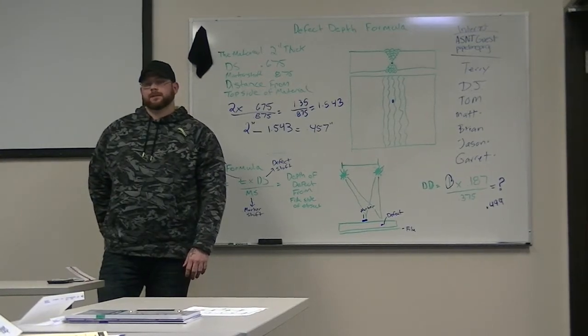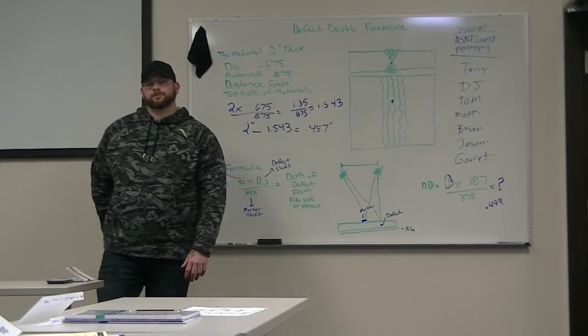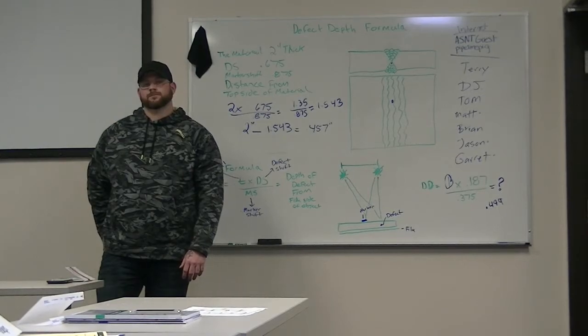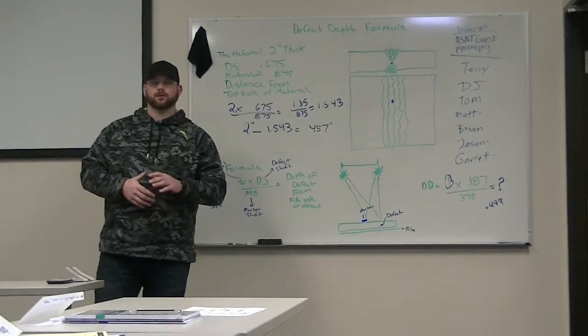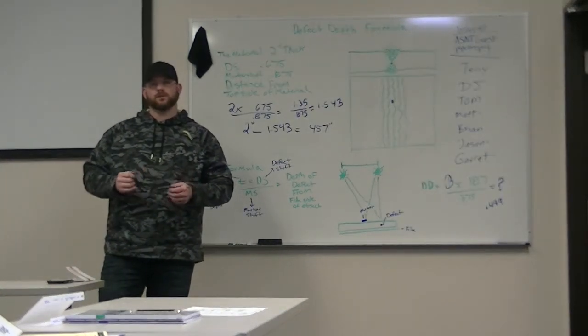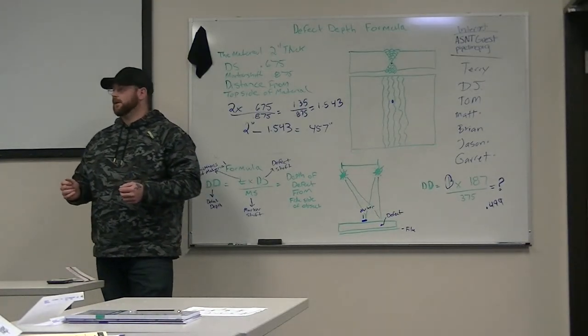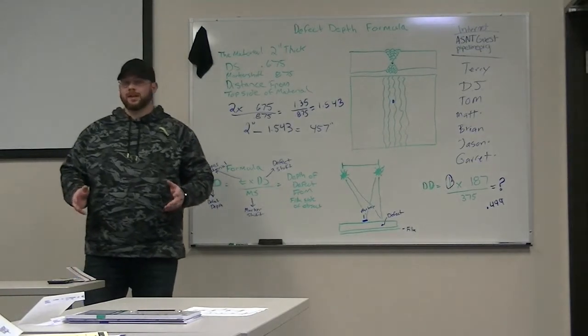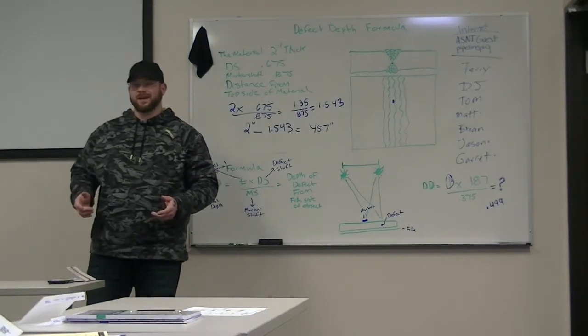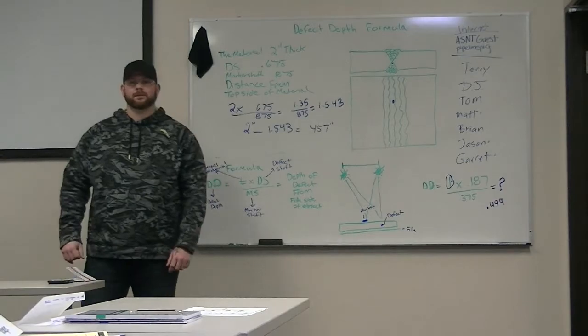I know a lot of machines, maybe not radiography, but UT and ET, do all the calculations for you. There are some aids when using exposure times. There are exposure charts. There are slide rules for gamma ray sources that can help you approximate your time. And most of the time it is an approximation. It's not going to be exact, but it'll get you in the ballpark.